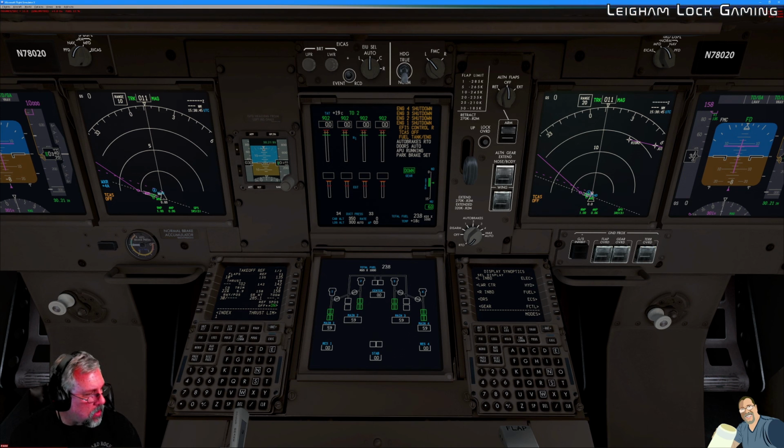we look at the main one and the reserve. So we have 5.9 metric tons and 0 reserves in main 1. And we look to see if that's greater than or equal to main 2, and it is not. And then we do the same thing for main 4. Is it greater than or equal to main 3? And it is not, it's equal. And in that scenario, we do not need cross valve 1 or 4 to be open. There's a lot of details in the FCOM, you can read more about it, but that's the long and short of it.